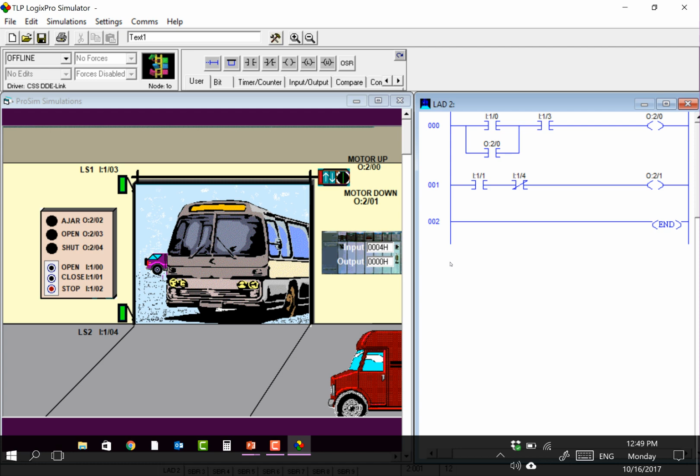Yeah, and when is it normally open and when is it normally closed? It all depends on the hardware you buy. So evidently, the person who bought these sensors for the top and the bottom bought two different sensors, right? So actually, this is a sensor that when the gate goes past it, the sensor pops out and closes the switch.